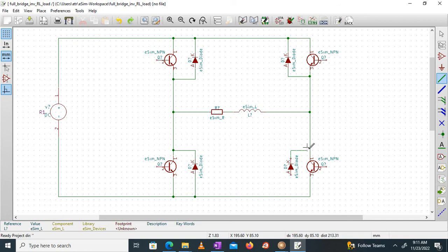See to it that wherever you place a connection there is a small junction formed, right? This green color dot which you see over here. So see to it that the connections are proper, or else later in the simulations you will find yourself in trouble. Alright, now I will require to plot various voltages, right?